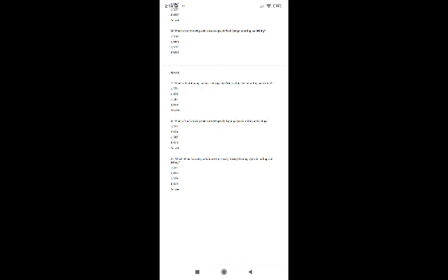Which of the following code is used to specify boring slash reaming cycle in milling and drilling? Option A G73, option B G84, option C G50, option D G85. So here the correct answer is option D, that is G85 code is used to specify boring or reaming cycle in milling and drilling.